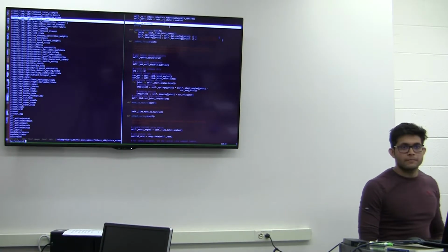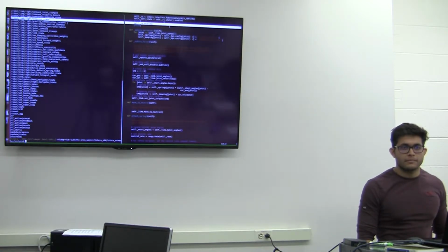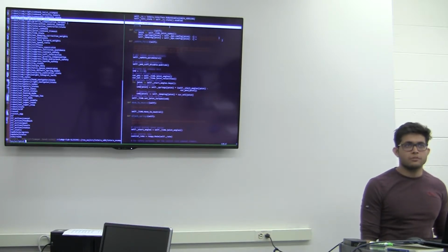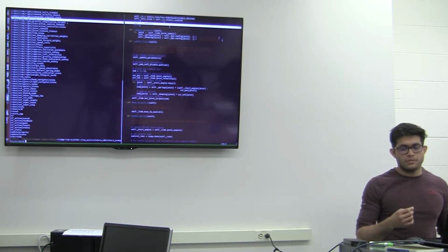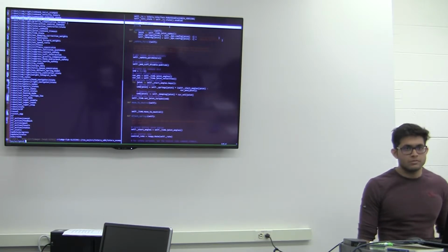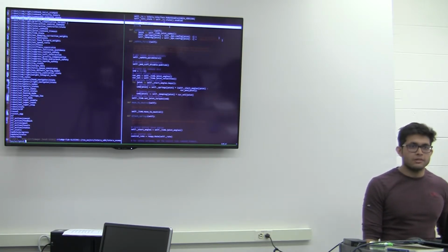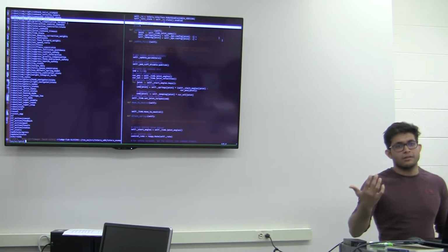Excuse me. So how will you get the position, like if it's tracking a keyboard tag, for example, from the camera, how will you get the position in the world coordinate frame? Because you know the position in the camera coordinate frame, and you know the transform, you know where your camera is. Okay, so do we have that as an inbuilt function, or do we have to do it? Yeah, I mean, if you are using an external camera, you have to do it.